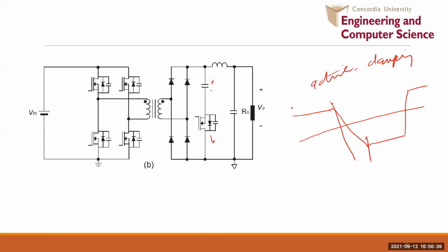So during that time you turn the switch on, and the current which was flowing through this now flows through this. So it is short circuit, and whatever this pre-charged capacitor voltage will appear across them like a capacitive output filter.